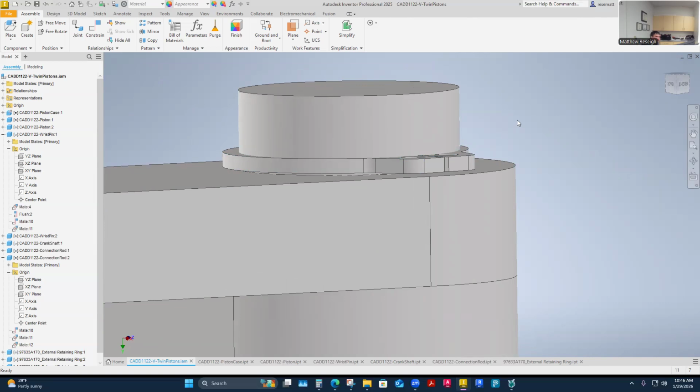Sometimes it matters how my 3D printer prints versus how your 3D printer prints. What is the type of material that you're printing with, and what is its normal tolerances? There's a lot of things that go in here to make this thing fit on here. It takes a little bit of brain power to figure this out.